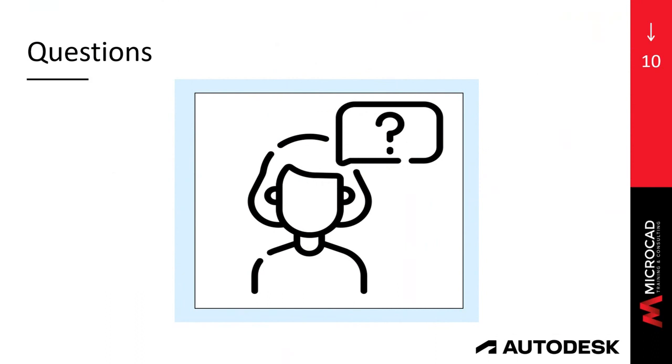Thank you. The second question is, what is your recommended workflow? Again, a very cool question. I would either start from Forma. If I have a big site, I would start in Forma. And then Forma links directly, and I can export whatever I created in Forma out into Revit. And from that point on, continue developing my design and transfer those mass elements into walls, doors, and floors, and roofs, and everything else that I need in Revit.